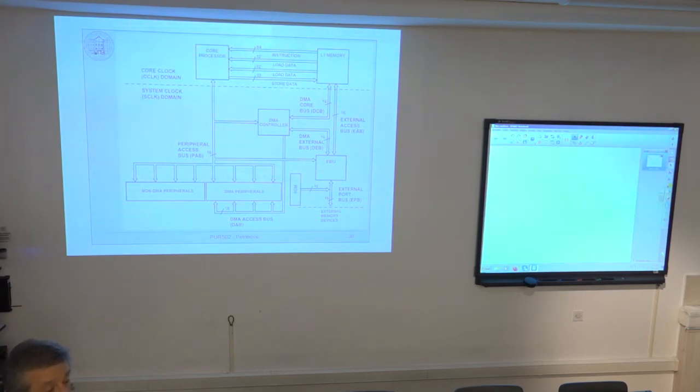So only if the whole block was loaded, for example, 128 data values are loaded into memory, only then you would activate the interrupt and the processor would process the whole block immediately. So this is the way to increase the efficiency. The CPU core does not have to service each particular data sample coming to these high-speed peripherals.